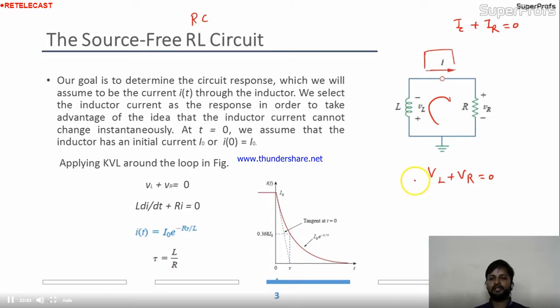Now, do you have the relation between voltage and current for the inductor? Yes, you have. This is nothing but L di/dt. And VR is nothing but Ri. So if you solve this differential equation, you will get i(t) is I naught e to the power minus Rt by L, where tau is nothing but L by R.